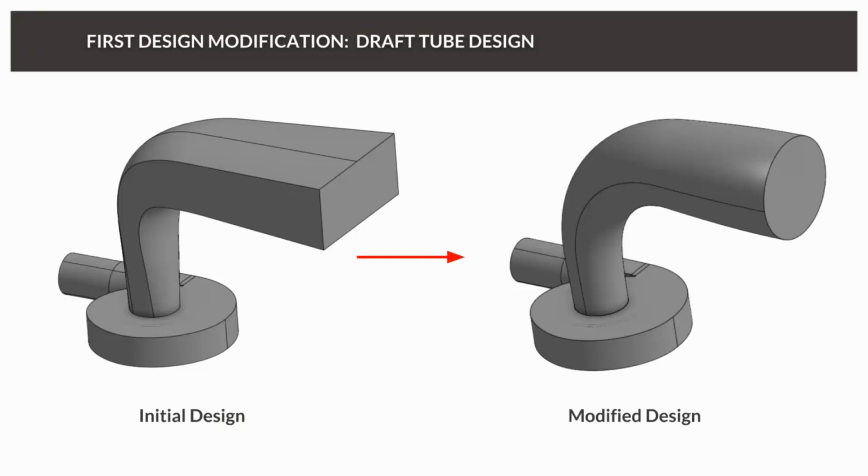Okay, so what we're going to do is a quick design comparison. We've highlighted two areas of interest, or two areas where we had questions, from being able to see inside the product using CFD. One is the angle of the stator blades. Can we reduce the recirculation on the tops of those blades? And will that improve our efficiency? Will we extract more energy from the water? And the second is the design of the draft tube, which wasn't great.